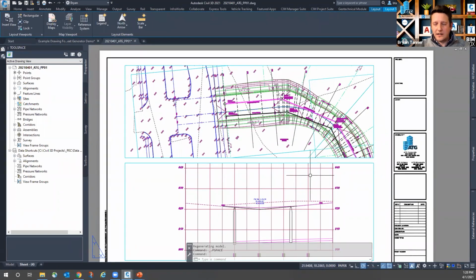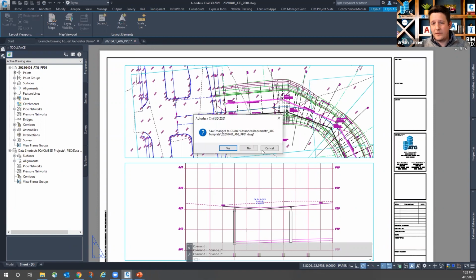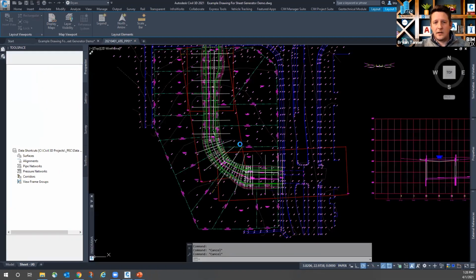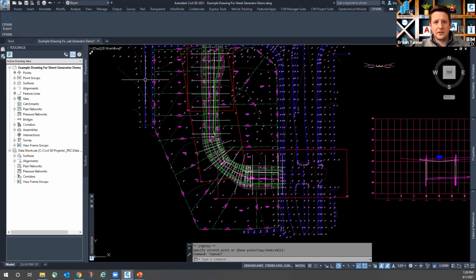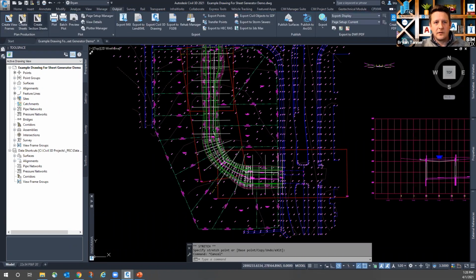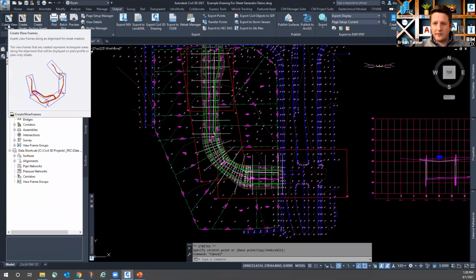If you're at the beginning phase of a project and you're just cutting these sheets for the first time and you haven't done any additional work, then maybe it's not an issue. Maybe it's easy enough to go back into your model drawing, make those rotation and positioning changes and recut those sheets fairly quickly. If our feature settings and our command settings are defined properly in Civil 3D and we don't have many changes to actually make and adjust from our dialog boxes, then we can run through this process in a matter of a few minutes. And it's really not detrimental to our productivity.